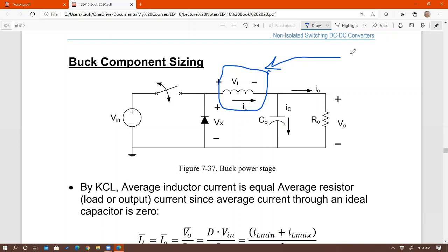Are you asking for the inductance? Yes. So I'm asking, when you go buy an inductor, what do you need to know? The inductance. Yes. What else? Is that it? The maximum current the inductor is going to see. You're going to want to make sure it's rated for that. That's correct. So those are the two things you need to be able to purchase an inductor.